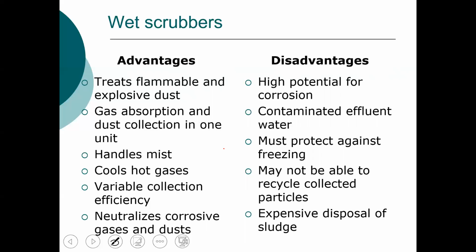And another issue is that because your contaminants are now in water, they're moist, so it may make it more difficult to recycle that material. So if you think of that drop box, if we're looking at aluminum chips or material from a foundry, we want to recycle that. But in the case of a wet scrubber, that material is mixed with water, it's wet, we have to dry that before we can recycle it.